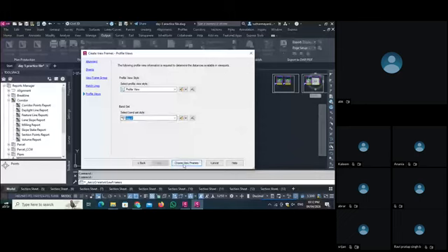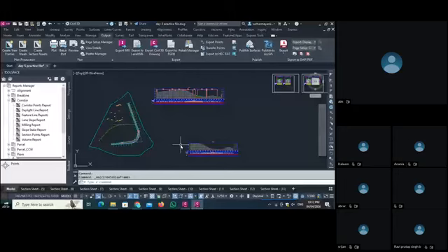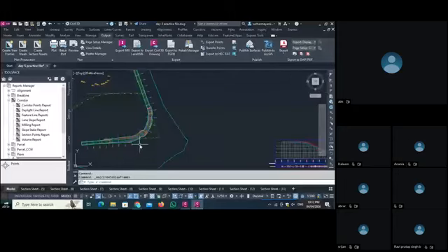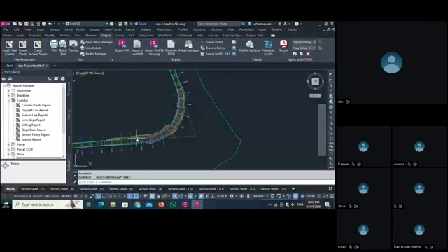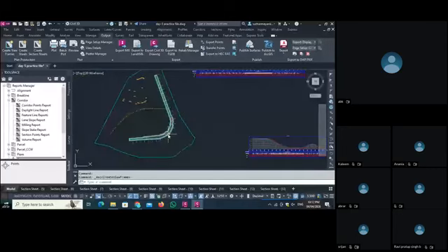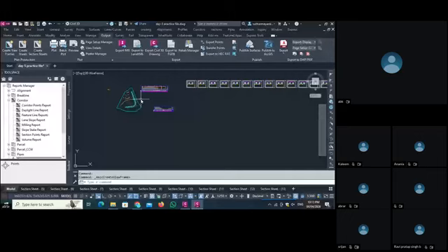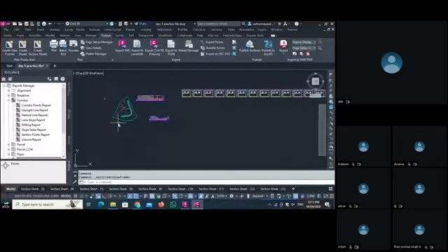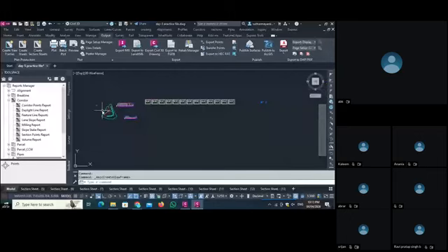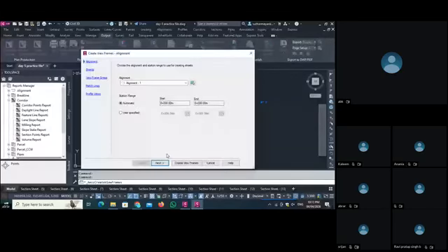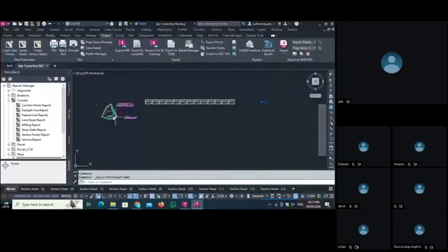create view frames. As I create the view frames, see why this view frame is not selected, not created, as we have to set our screen like this. Then we create a view frame. Once we create a view frame, we go here to the create sheet section.